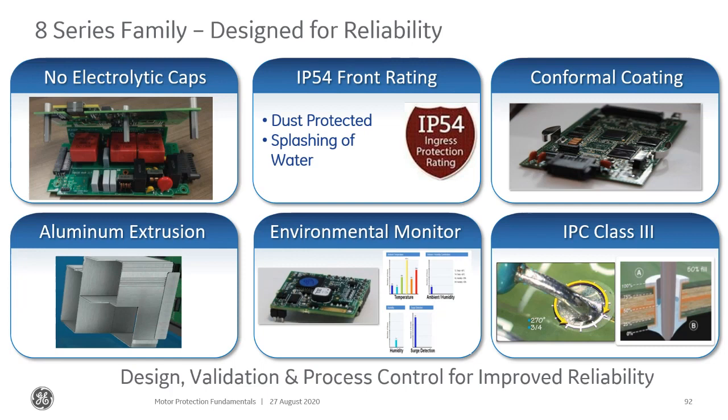We've also used the IPC Class 3 manufacturing standard. This has to do with circuit board assembly, and especially has to do with soldering, the amount of solder that gets put into the circuit board. This is basically an automotive class of manufacturing.